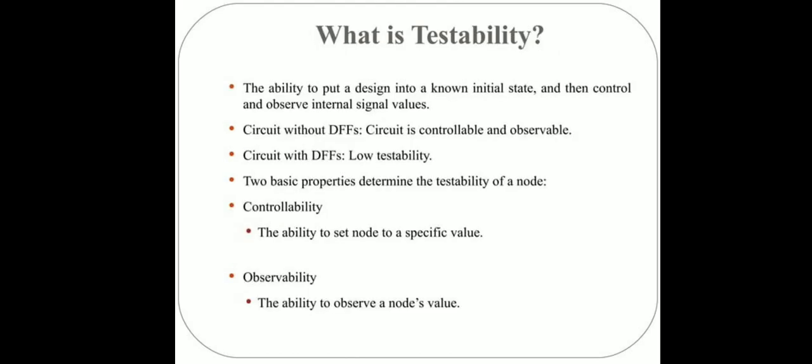And what is testability? By designing a chip with testability in mind, it becomes easier to identify the structural defects in the chip and fix design errors before the product is shipped to the customers. Designing a chip with built-in testability features can make the testing process more efficient, thereby reducing the cost and time required for testing. This can lead to significant cost savings during the manufacturing process. Also, by incorporating DFT features into the chip design, it can help to identify any defects early in the process, which allows for faster repairs and improvements in production yield.